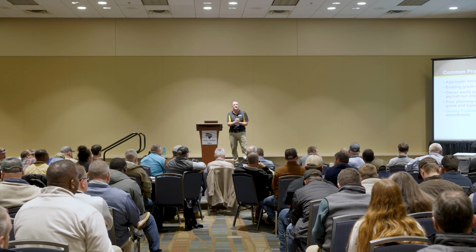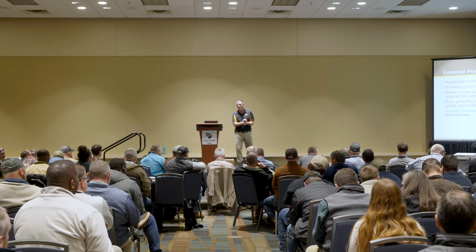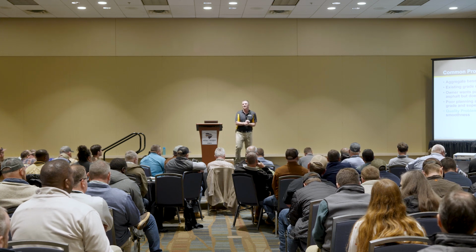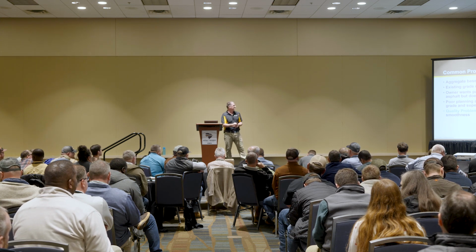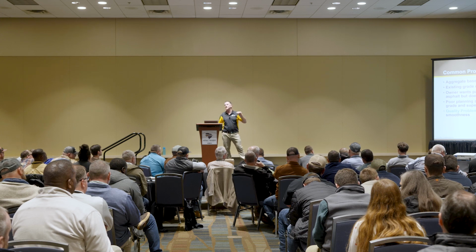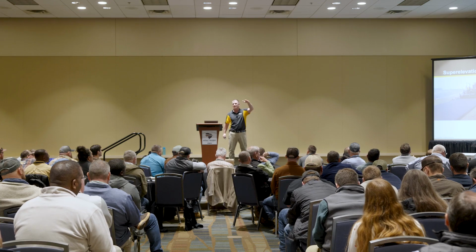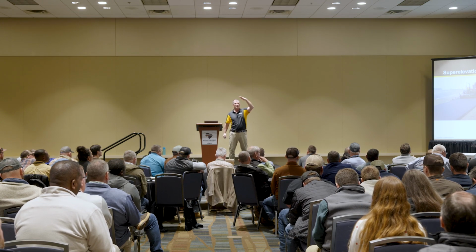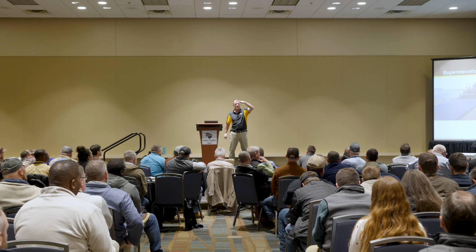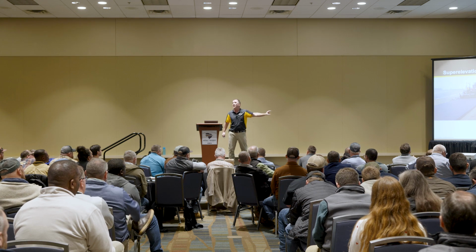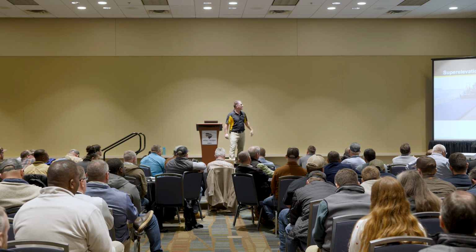Because when you're out there and you got trucks lined up and everybody's under the gun, under pressure, it doesn't always go so well. And then the other big thing to think about again is that compaction. I keep mentioning it because people kind of tend to forget about it a little bit. When it comes to paving it in, we've got variable thickness, we're going to have variable compaction. So I may have to be a little thicker in an area so that when I actually roll it, now my profile, my slope all the way across is the same.